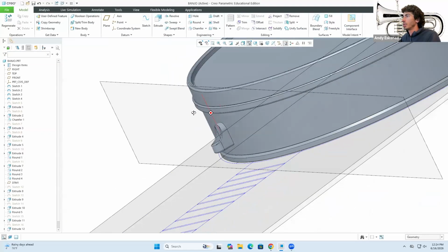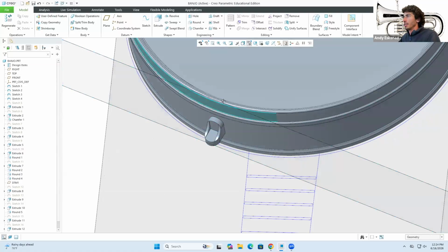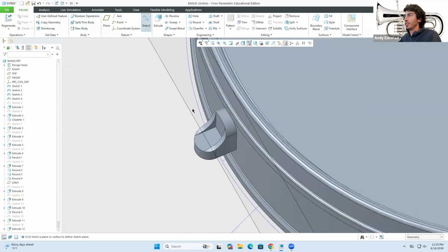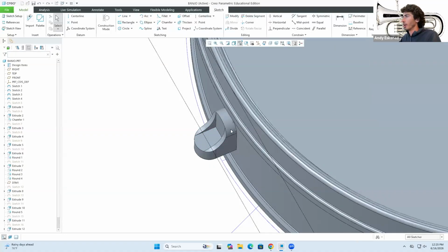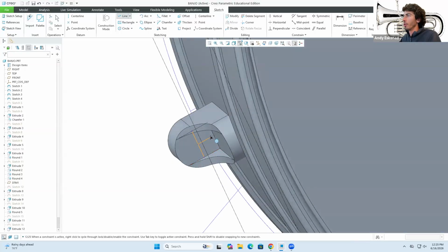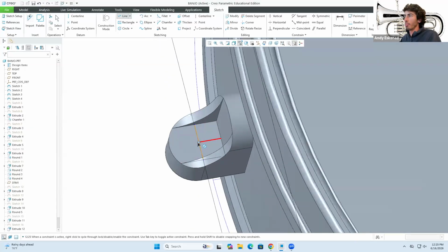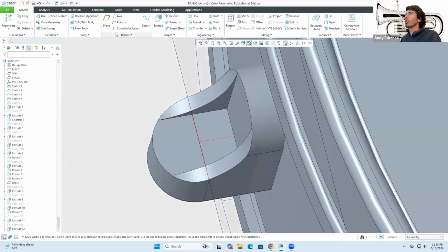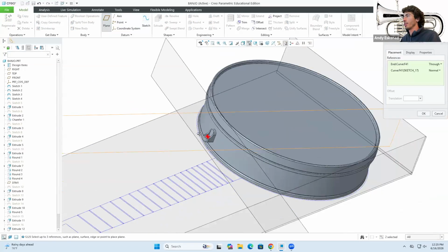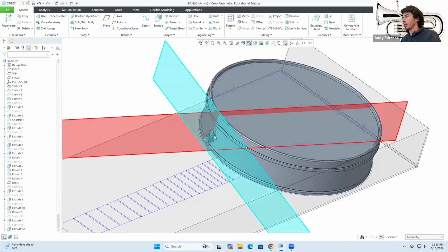So what we can do is now, let's see, what would be the best approach here? So I'm gonna do a sketch in here, and suppose that you want this to happen from the very middle, right? Which would be that point in there. So now I can go here to plane, point and line. And now you have a new plane that is right there.